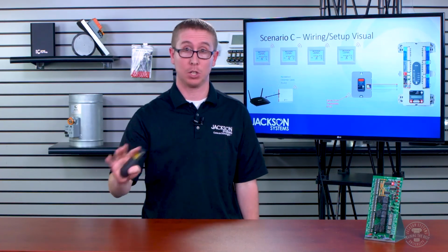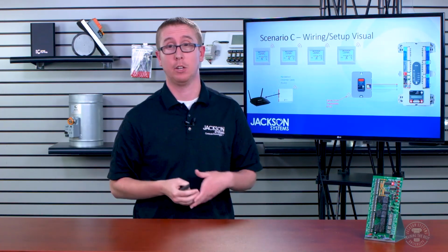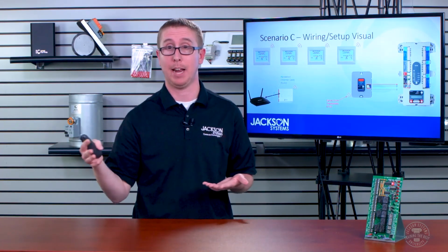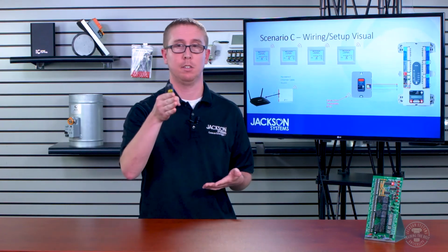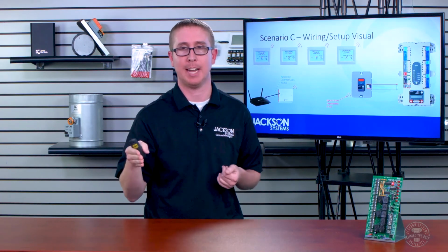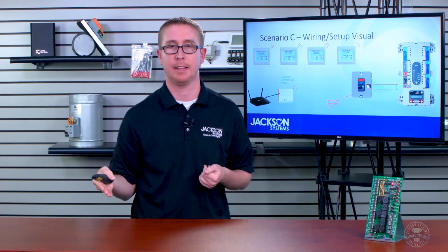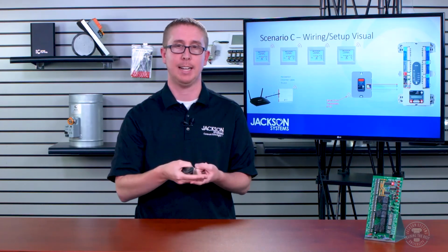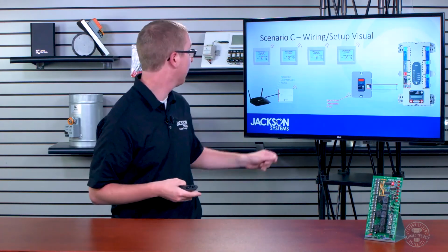Here's kind of what that looks like. So again, there's the HZ432 panel. It's just 4 wires from the wireless zoning adapter to the panel that you'll see there. That panel is getting RedLink signals from both the thermostats and this gateway here.